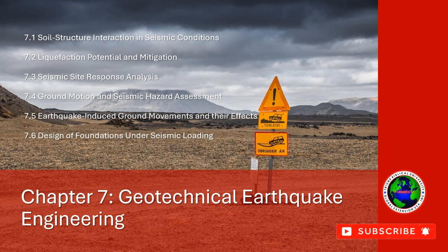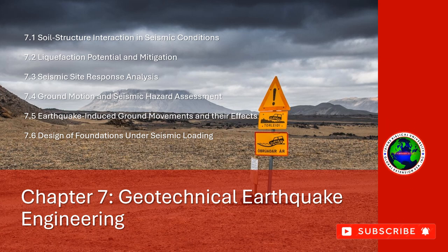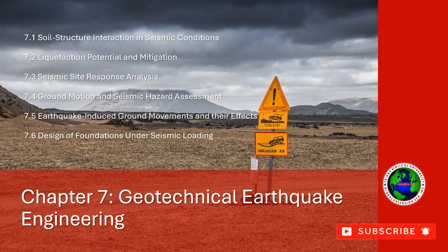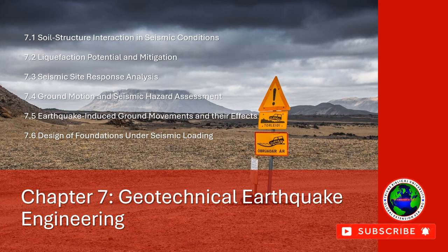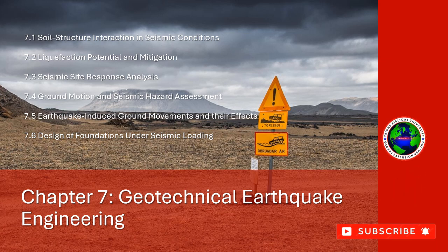7.6.5 Mitigation strategies for foundations under seismic loading. To reduce the impact of seismic loading on foundations, several mitigation strategies can be employed. 1. Base isolation. Base isolators can decouple the foundation from seismic forces, allowing the superstructure to move independently from the ground motion. This reduces the stresses on the foundation and prevents excessive damage.